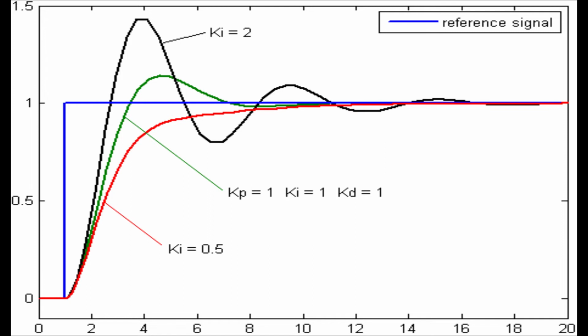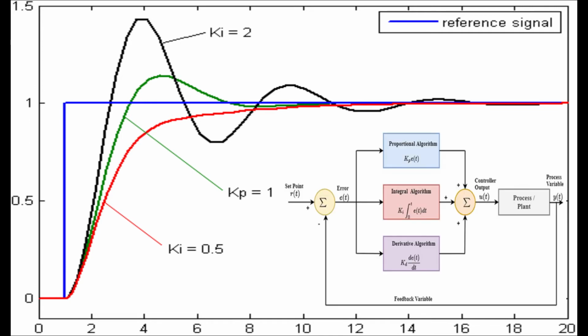Now coming to the Kd value. It is the derivative of the error function with respect to time. You can understand its physical aspect by looking at the response graph obtained after PID tuning. As you can see, the derivative graph never really approaches zero or a baseline. Kd value adds into the stability of the system. It basically reduces the overshoot of the drone from our desired endpoint.